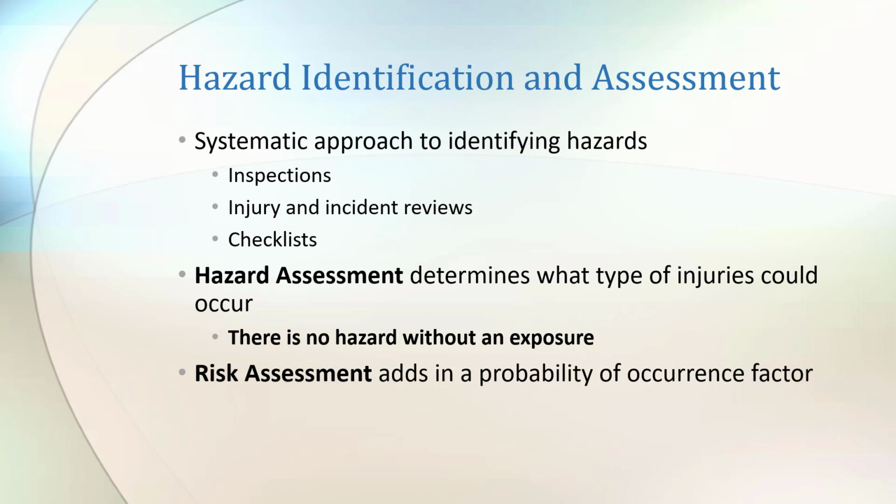If you have a fan, whether it's a large fan or a small fan, OSHA has a requirement that says that the fan blades, the rotating blades, will be guarded. That means they have to have a cage on them or something like that. And there are certain regulations on how deep it is and how wide.